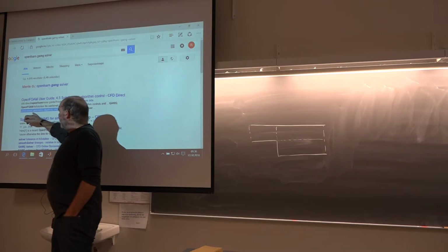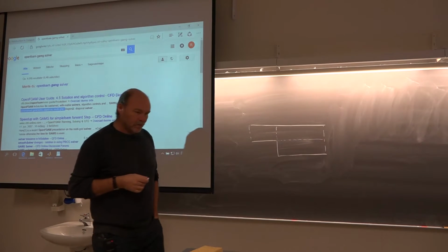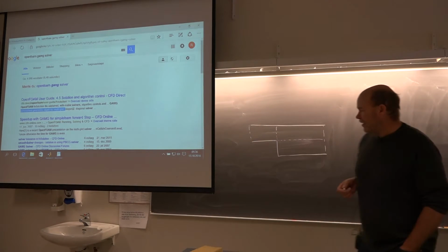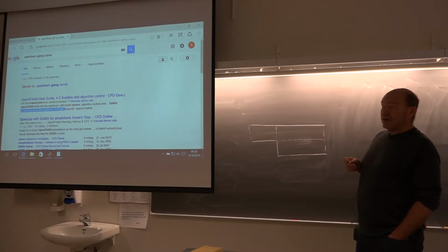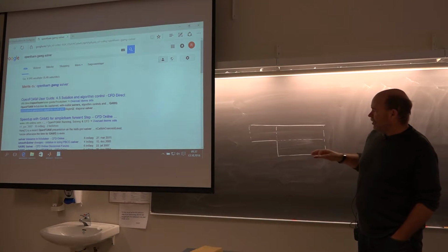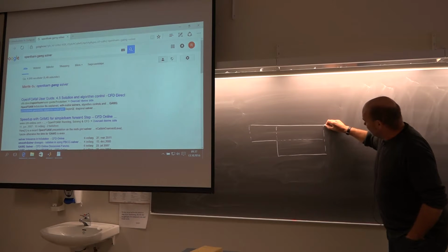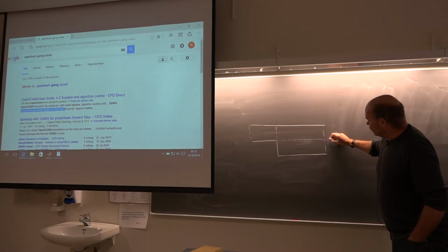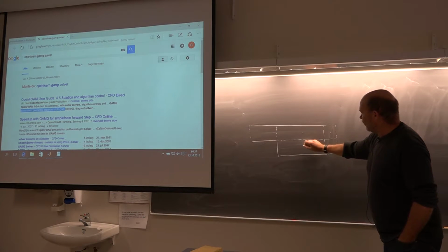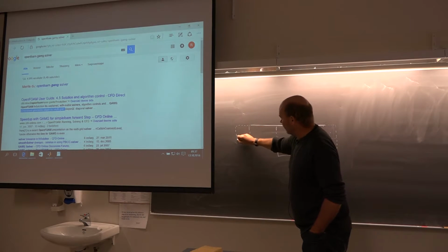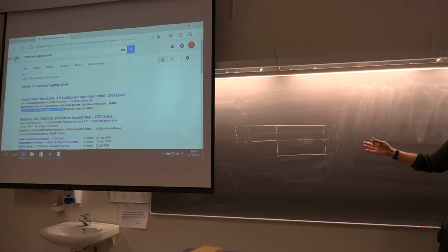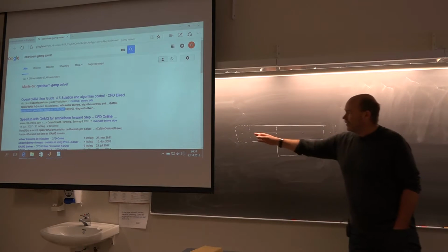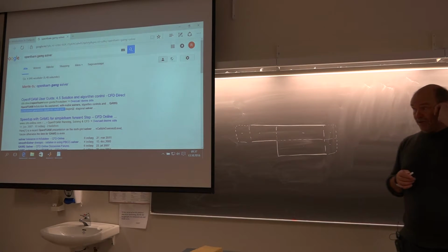Here, the generalized geometric algebraic multigrid solver, what does it mean? It means that we have given the problem to a mathematician. If we do this problem ourselves, then we would use the geometrical problem here. Maybe construct ghost cells here to have boundary conditions, and then even a ghost cell here. And then we would have programmed it like this for all the different grid levels, getting the boundary conditions into the equation system.